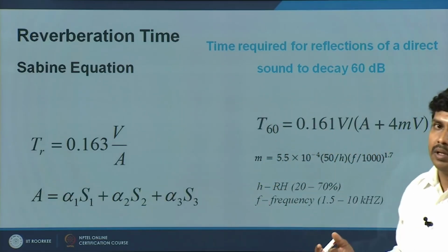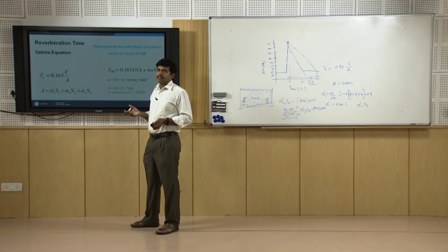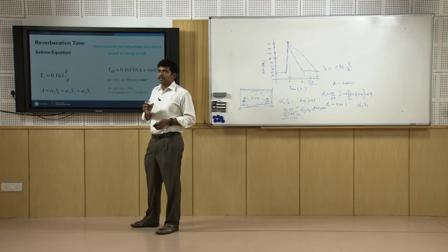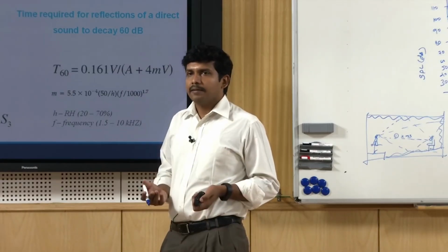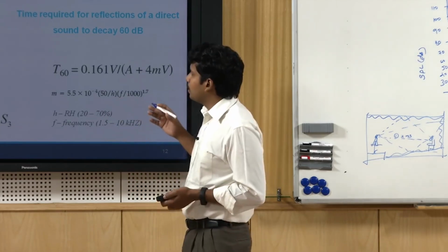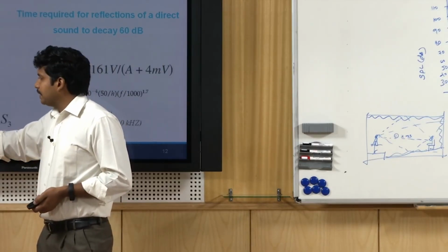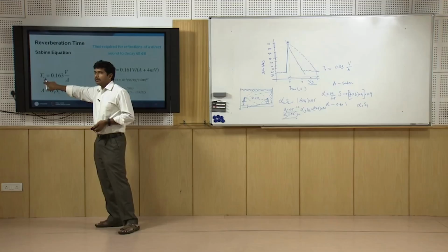If you take large auditoriums, cathedrals, opera houses, they are huge in volume, and the reverberation time will go as high as 2.5 seconds, whereas in small lecture halls, small rooms, the best designed hall, say a classroom, would have a reverberation time expected around 0.8 to 1 second. Less than 0.8 you will have a better audibility. We will look at audibility more in detail, but simply speaking this is a relation between the volume, surface area of absorption and the absorption of the material. These three things determine the reverberation time.